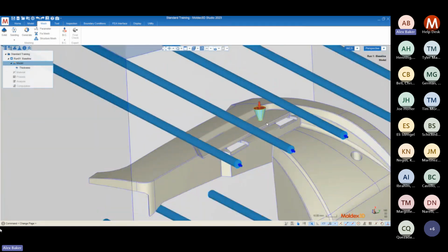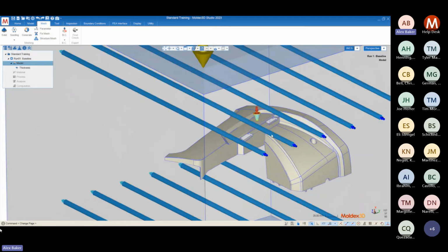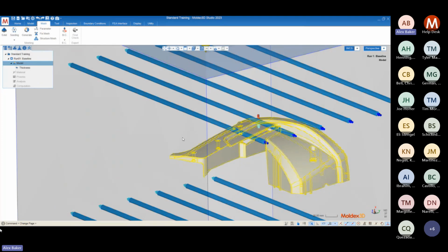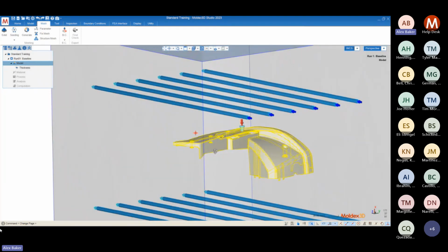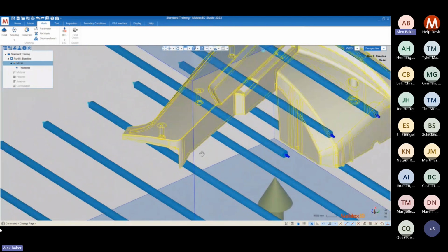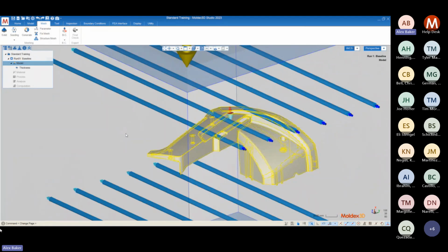Because of this line-defined technology, we don't have to create a surface mesh for these objects. They just receive a solid mesh, and I'll explain how that interaction works once we get there in the solid mesh parameters. But for geometry objects like our part here, we will be specifying the parameterization for two types of mesh, which will be the surface mesh and the solid mesh.